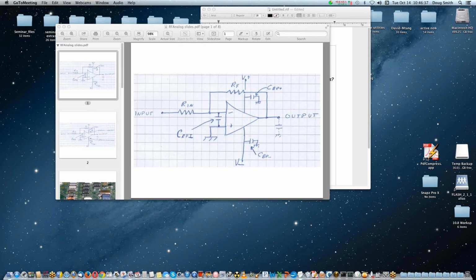generally shielding of op amps is not something I've seen people do, and I haven't done myself. I suppose I have worked on op-amp circuits for a Mars mission that used gig-ohm resistors, and their frequencies were in the audio band, but when you talk about gig-ohm resistors, boy, parasitic capacitance to everything, including a shield, affects the circuit response at baseband, and that's an interesting problem. But most of us, thank goodness, don't have to deal with gig-ohm resistors in the circuit. Hard to find, too. Yeah, I mean, gig-ohm resistors. Single-digit picofarads are a problem at audio frequencies with resistors that big.